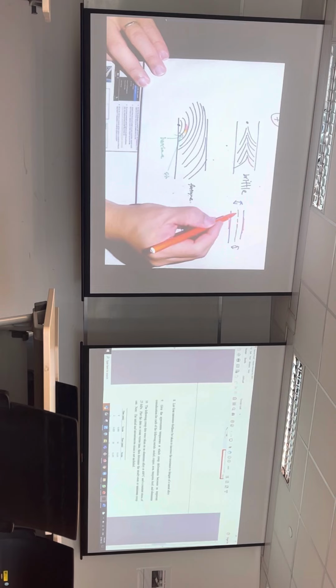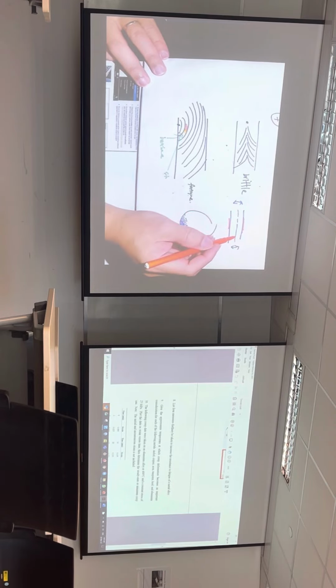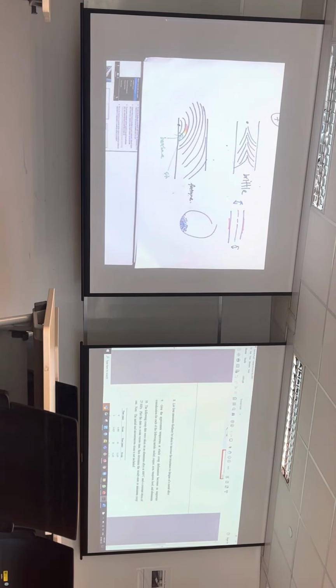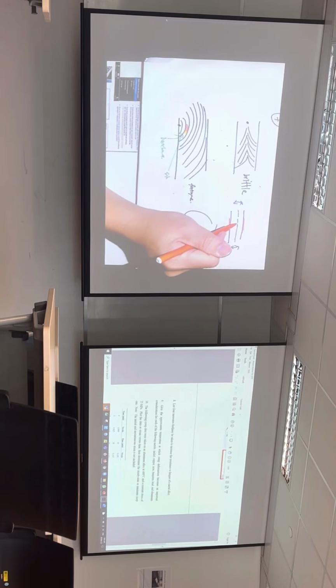The center will be like a neutral axis, right? Yes. The center doesn't flex. The outside is always the one that flexes, and the further away you are, the more you have. That's why these are the parts subjected to more stress. So for those flexing actions, usually the crack will not emit from here unless there are a lot of defects.